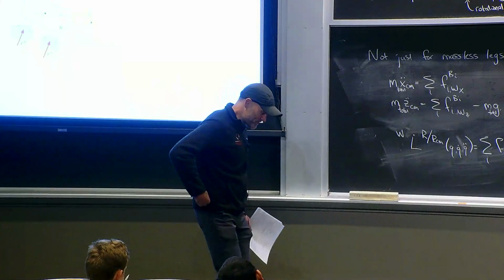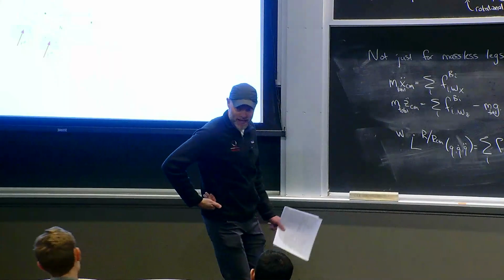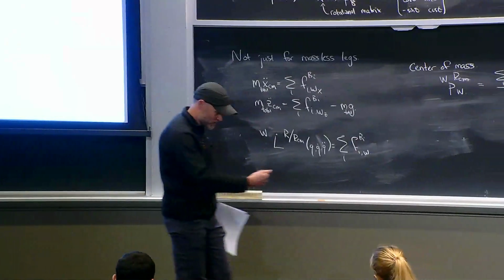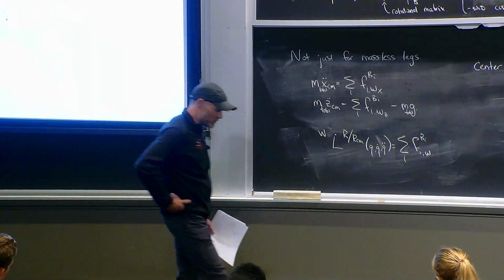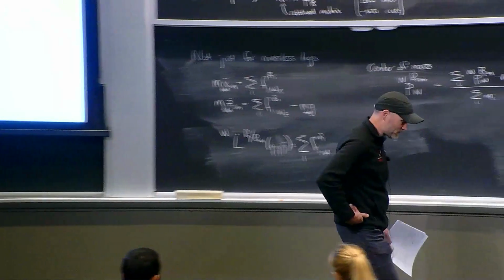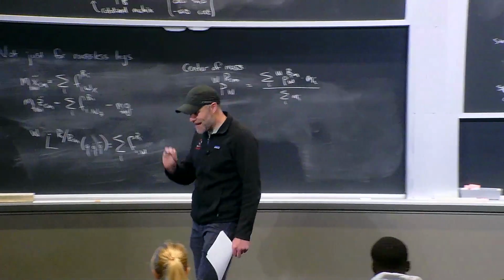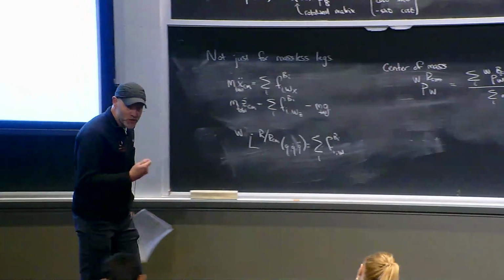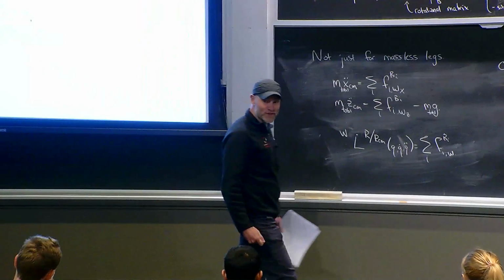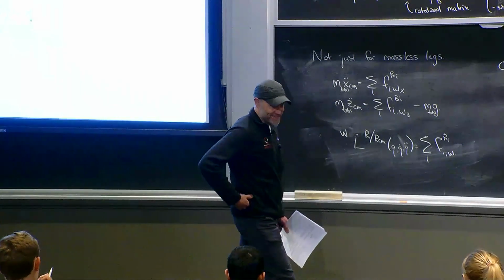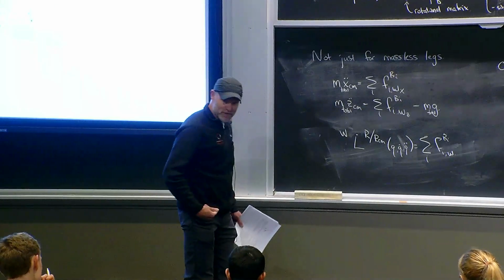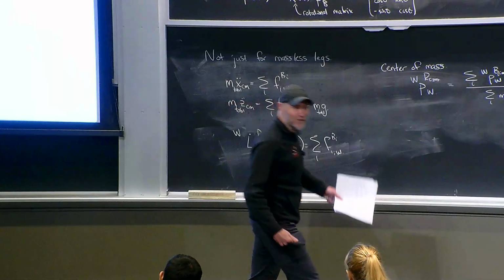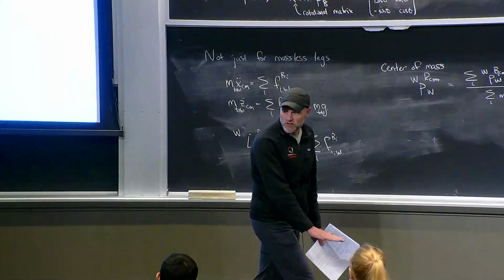And here's why. If I'm going to regulate my center of mass, and I say the acceleration of my center of mass is 0, or my center of mass velocity is 0, which is what a lot of these robots do when you see them walking around like this, if your center of mass doesn't accelerate vertically, then in order to achieve that, you have to set your foot down so slowly that there's no impact. And you can do that if you have enough degrees of freedom. No matter what speed you're coming in at, you can start lifting your foot right before you touch down to touch with almost 0 velocity.